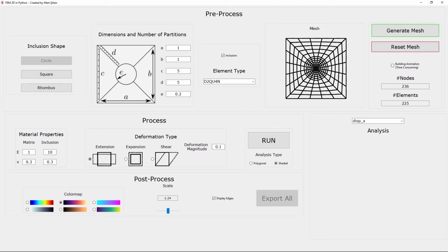And I also would like to mention one thing about this. So circular inclusion. As you can see, this section was void instead of being full of elements. Now, the way you have to code this is that you have to combine the uniform mesh and then the mesh with the inclusion. So the thing inside, as you can see, we have these 5 elements? Yeah. At the very middle, we have a square, which has 5 elements inside in each edge, let's say.